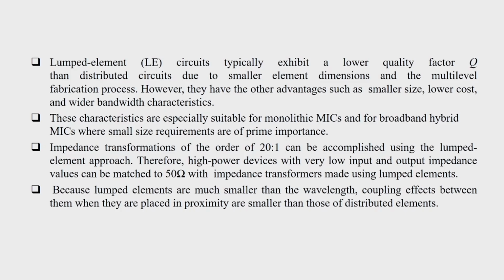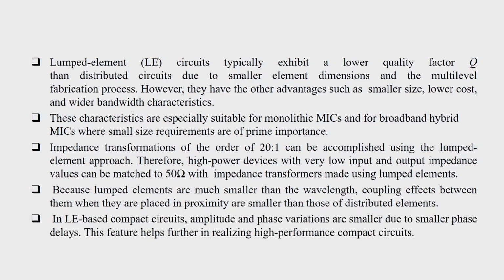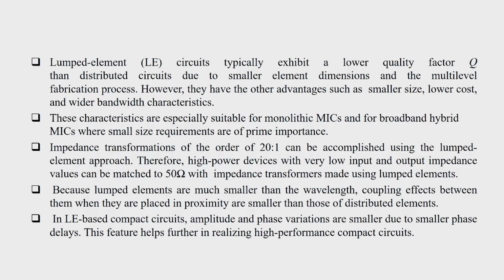Because lumped elements are much smaller than the wavelength, coupling effects between them when they are placed in proximity are smaller than those of distributed elements. And in LE-based compact circuits, amplitude and phase variations are smaller due to the smaller phase delays. This feature helps further in realizing high performance compact circuits.